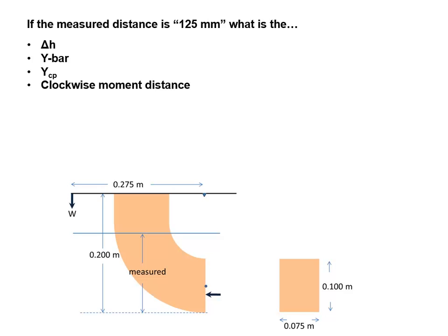Okay, so our theoretical hydrostatic force that we had measured was 1.802 newtons. And the actual force was 1.756 newtons. Divide by 1.756 newtons times 100. In this case, if these had been our measurements, if we had measured a depth of 50 millimeters and a mass of 115 grams, then the percent difference would be 2.7%, meaning that the theoretical force was too high by 2.7%.